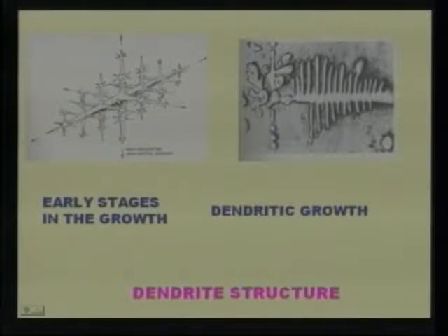The grain structure is developed like a tree, stems, and other stems are formed. These crystals are absorbing the smaller crystals and forming bigger crystals. Like that it is developing as a tree. The heat dissipation will be taken in all the directions, towards the smaller crystals.